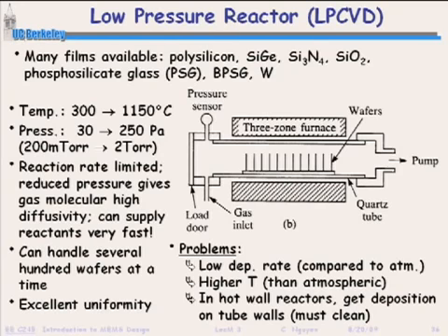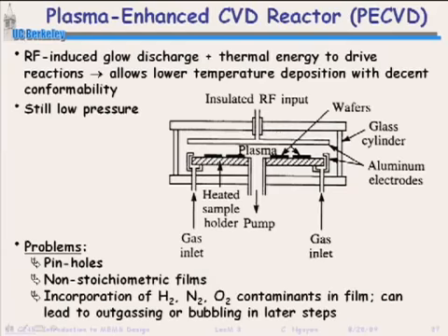You can also do plasma enhanced chemical vapor deposition. This is maybe number 2 in preference for deposition. What this is doing, for this whole process, for these reactions to occur, you need energy. You can supply energy by temperature, but you can also supply energy through a plasma. And so that's all this is doing. This is putting the energy in for reaction through both temperature and the plasma.